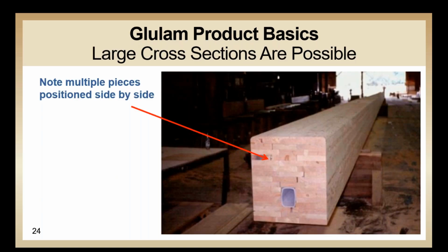As I mentioned, glulam beams typically come in widths ranging from 2.5 inches to 10 3/4, but that doesn't prevent the manufacture of wider glulam beams. Here's an example of a 21-inch wide by 27-inch deep by 110-foot long glulam. This is actually a column. You can see in the photo that there are multiple plies in each layer in the makeup of this member.